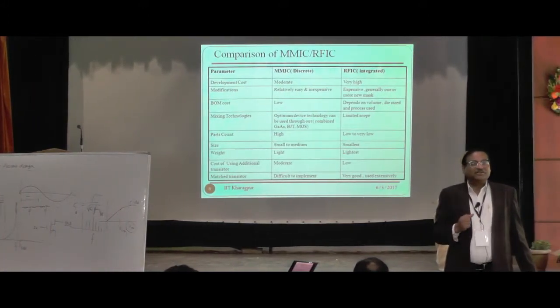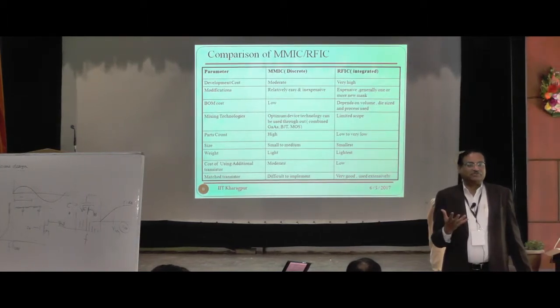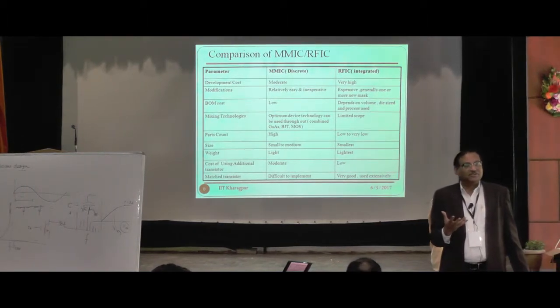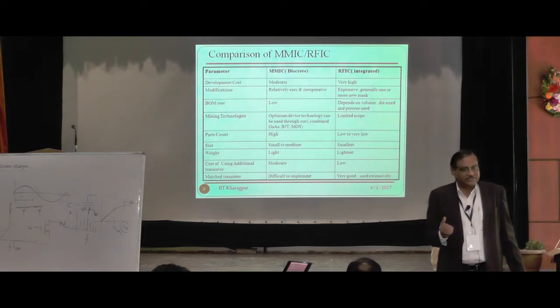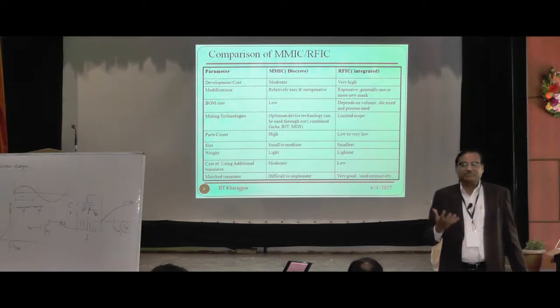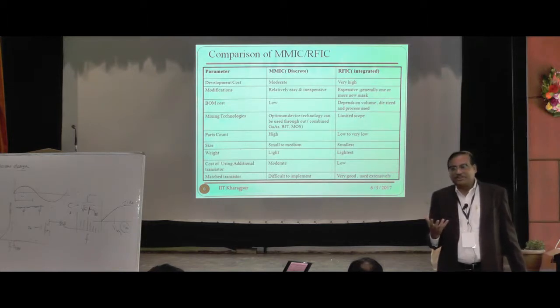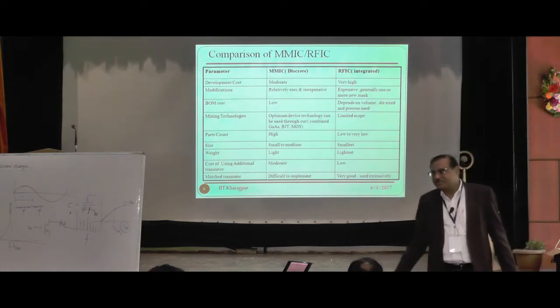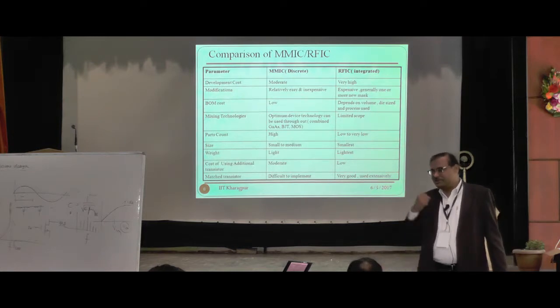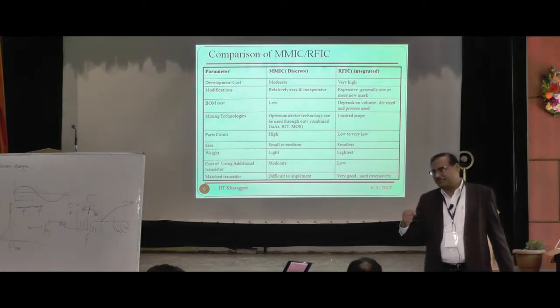But for an oscillator, the Barkhausen criteria tells you that you don't need any energy like that, but that is basically the ideal case. If you exactly satisfy the Barkhausen criteria, then the oscillation buildup will last a few nanoseconds. After that, the oscillation will stop. You need some additional energy to feed it.